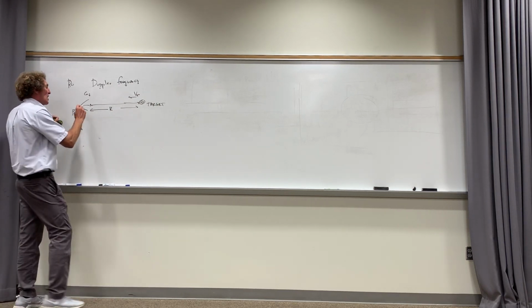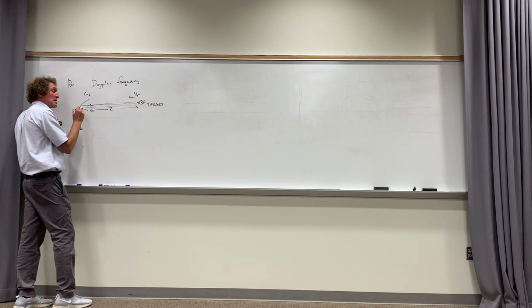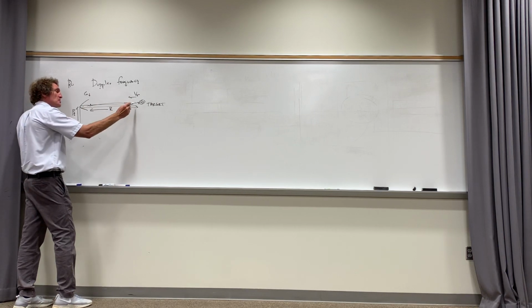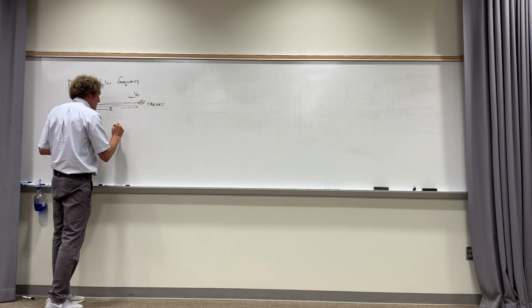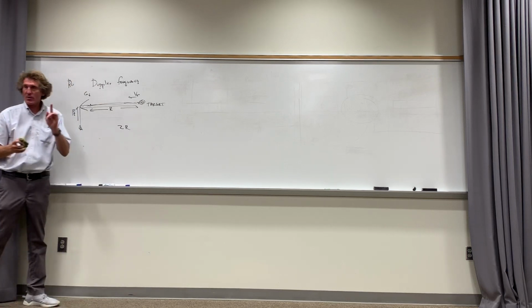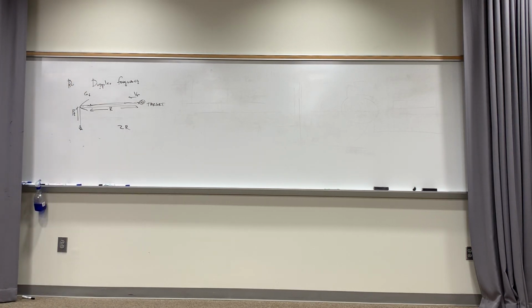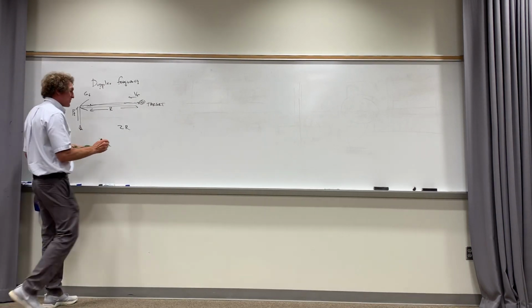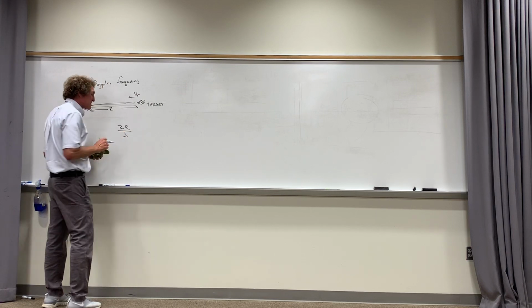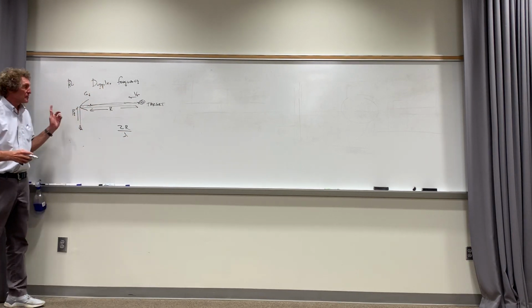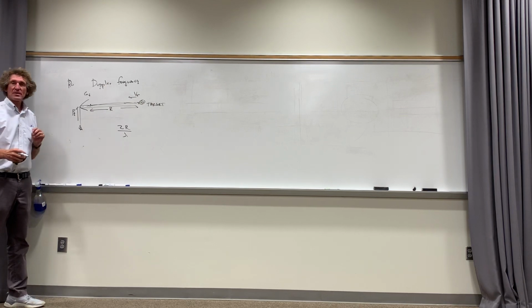Now what we're going to do is this. We're going to say, how far, or what path length, does the signal travel over one pulse to recovery? Well, it would travel over 2r. Do you agree with that? It has to go out a distance r, hit the thing, and reflect back, right? Y'all with me on this class? Yeah. So now, because we want a Doppler shift, we're going to get how many wavelengths are involved first. So if I divide this by the wavelength, say a wavelength is a meter and it's 10 meters away, that would be 20 divided by 1, or it would be 20. Do you follow me on this?